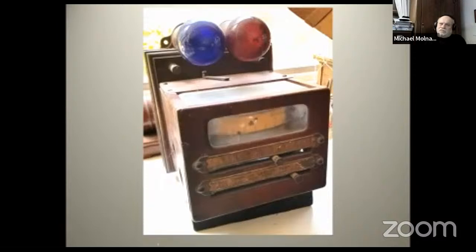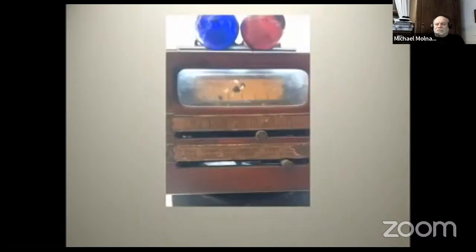This unusual device is an Edison pressure indicator. It was used in power stations and is described in the book Dynamo Tender's Handbook, written in 1892. It was known that varying the dynamo outputs would shorten the life of the incandescent lamps of the power station's customers. This device could regulate the pressure, now called voltage, coming from the dynamos. It utilized a lamp in a Wheatstone bridge circuit and a galvanometer that would allow the operator to balance the voltages.